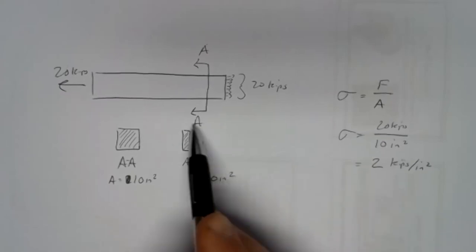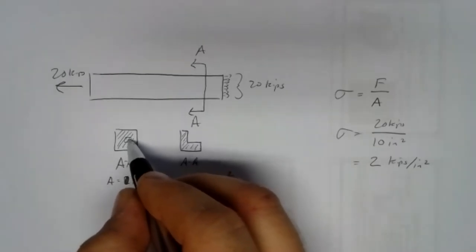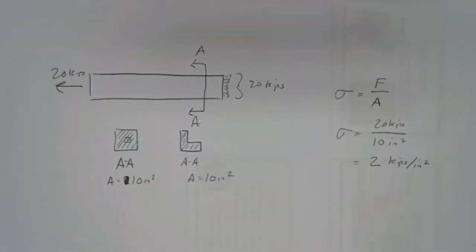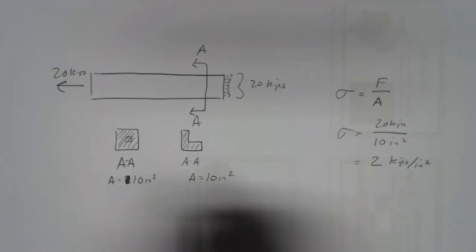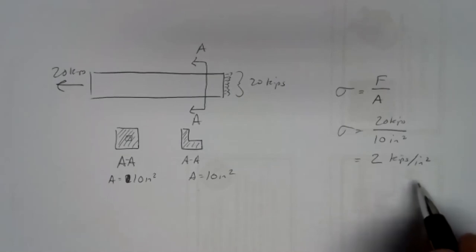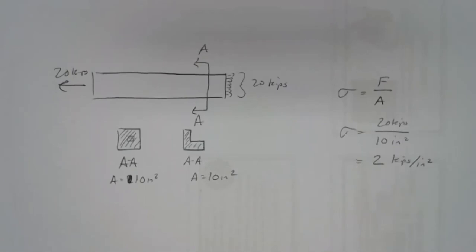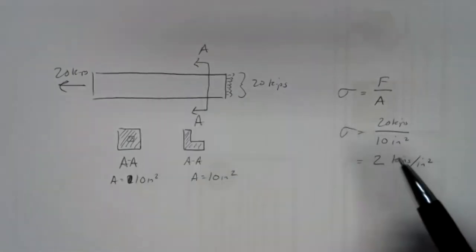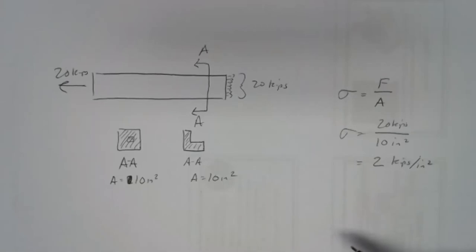We've lost the external geometry, and essentially we're zoomed in so close that all we're looking at are the molecules that make up the structure. We've jumped into the internal structure of the member. So we've lost that detail of shape. And that's important because that means we can now apply it to anything. We could say, well, if I have this stress of 2 kips per square inch, maybe I could pick a different shape or apply that to a different situation. I know 2 kips per square inch is the stress that member is going to have to handle.